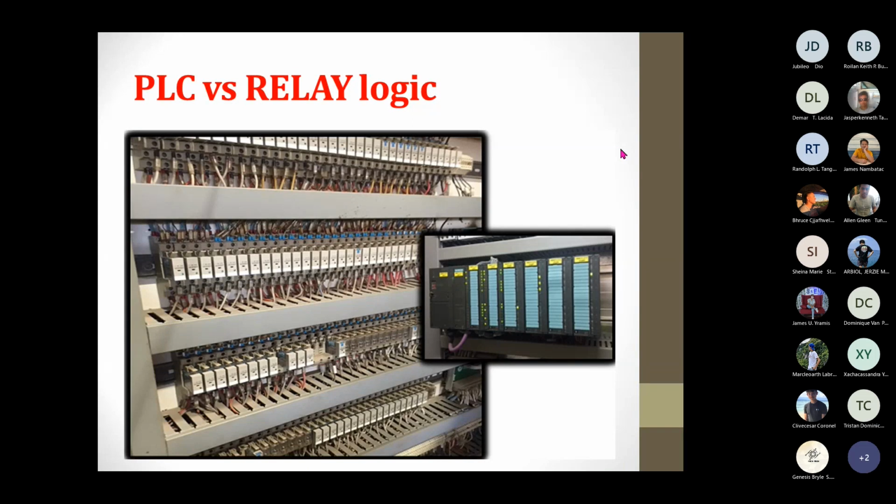If you can recall, for the sequence of the pneumatic system, for example in your midterm, you were asked to create A plus, B plus, and so on. So you use relays. In order for the pneumatic system to follow the given sequence, which is, for example, A plus, B plus, A minus, B minus, and so on, or depending on what type of operation you want, you use the relay, right? To enable the cylinders to run in this sequence.